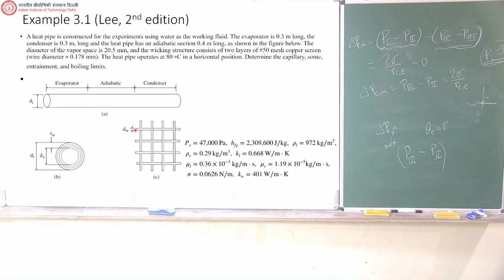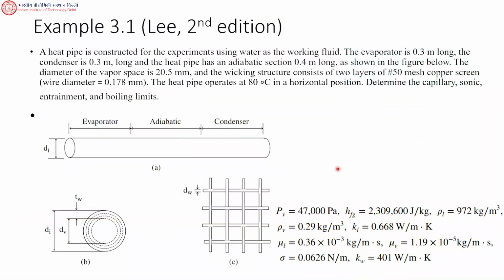Now, how do you make that heat pipe? What is the material of the body of the heat pipe? What is the wick material? What is the wick structure? And what is the liquid that you take in the heat pipe, and what are the various dimensions? These are the calculations that you have to do, right? And you have to make sure that, for the parameter range given to you, performance doesn't degrade too much, and the heat pipe does not fail, right? I'll ask you to read this for a couple of minutes.